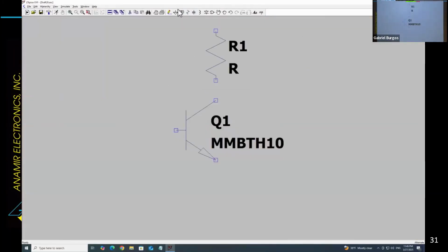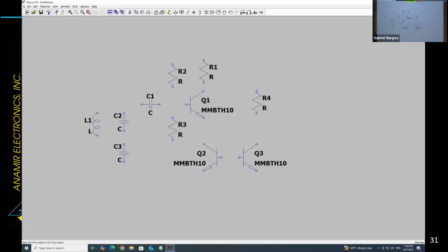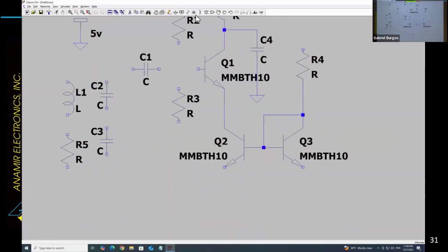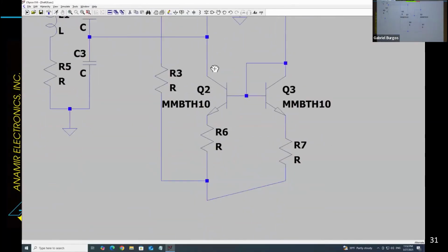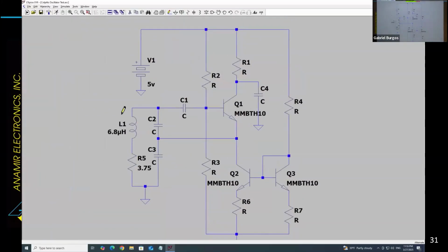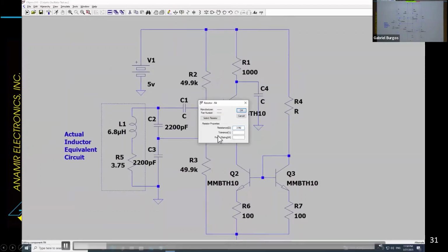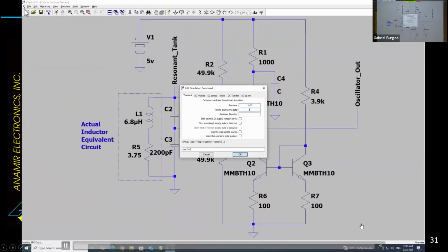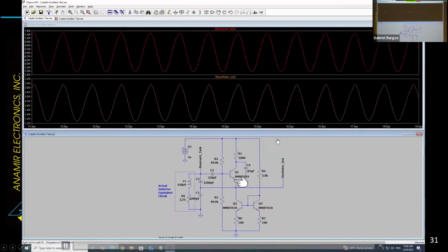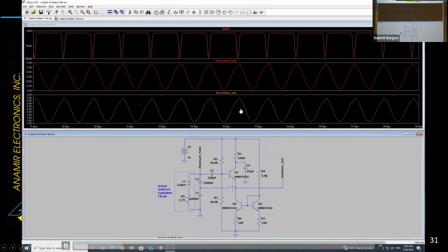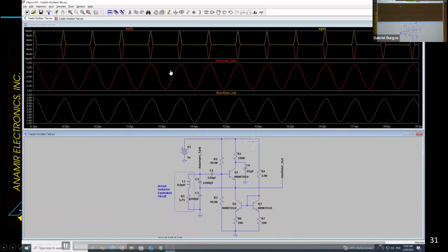That's just the standard LTSpice background. Oh, okay. So here I am building a version of a Colpitts oscillator. Oh, is that what that is? Yes, right. So I put together a model here, and I did it in stop motion. So we can see, now, one of the nice things about this is once I've built it in LTSpice, I can interrogate every signal.